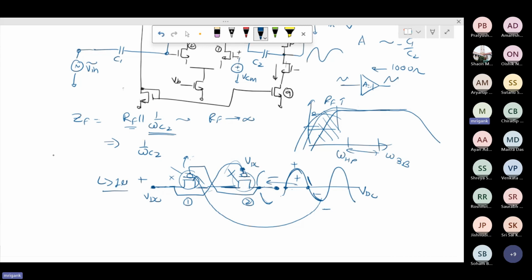In silicon, if you look at resistance values, the maximum values you can have using different resistors is, say, a few mega ohms. There are different types. There are metal resistors, which are made using metal segments. These have the lowest resistivity. Metal resistors are just small metal segments with very low resistance. So in case you need very low resistances, people use metal resistors.